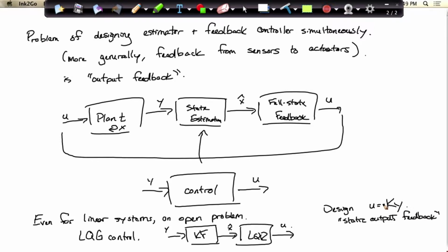I don't know how to do that for a linear system here. It's sort of shocking how few results we have here. LQG is the one example. And it happens that for linear Gaussian systems, if you're willing to have exactly the same number of states in my dynamic controller as my plant, then I have a Kalman filter plus LQR as a solution. And so that has justified us, in some sense, thinking about only feedback for a while. But really, there's hard problems that remain, okay?